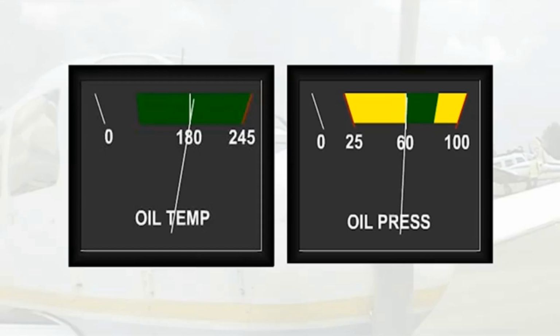Large fluctuations of the oil pressure gauge needle, on the other hand, will probably be caused by insufficient oil in the system. The engine may have been leaking oil, and eventually the level will drop to a point where the pressure pump cannot sustain its output. Then the pressure will drop momentarily until the pump can get some more oil, when the pressure will rise again, if only for a moment. Again, if the minimum oil pressure cannot be maintained, then the engine must be stopped to prevent damage.